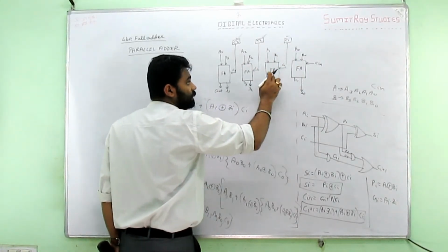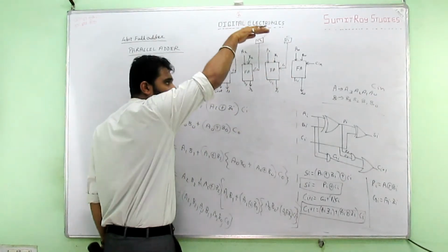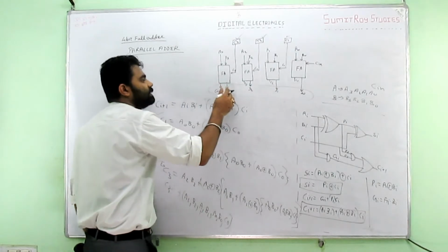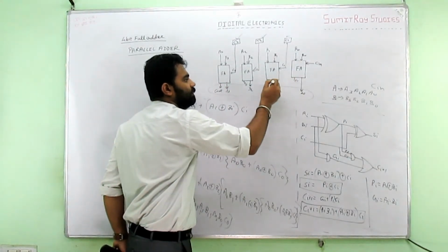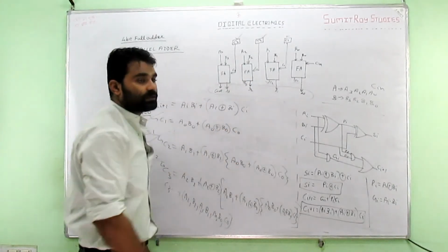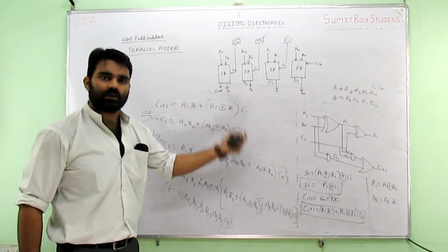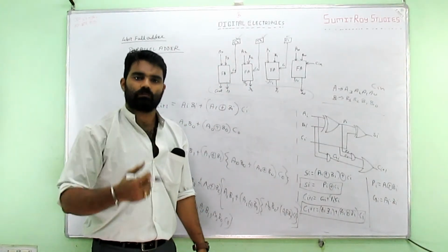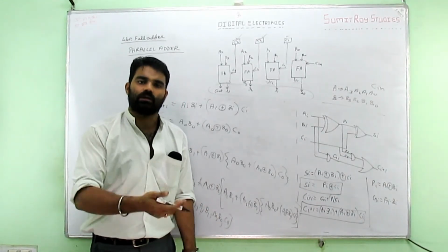We can develop these values, and now at an instant they can give output, because they already have the inputs. At an instant they can give output as S0, S1, S2, S3 and C out. Yes, obviously this will be available, but this is not required, so it will be discarded. So this is the available value at an instant. Let it be 10 bits. At an instant only it can give the outcome. Obviously the circuitry will increase, but at an instant only it can give the output.